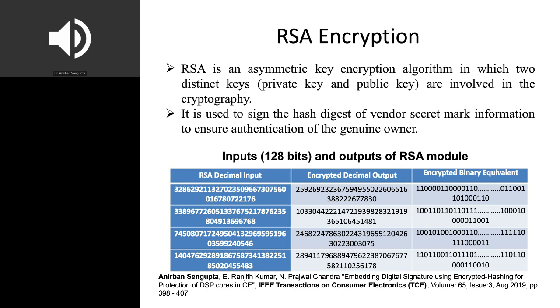The decryption process could work as follows: if you apply the public key, we can decrypt and get back to the hash, and then a second hash is computed. If both hashes match each other, then we know that the signature has not been tampered with. And secondly, only the actual IP owner would be able to perform decryption because he has knowledge of the concatenation process.